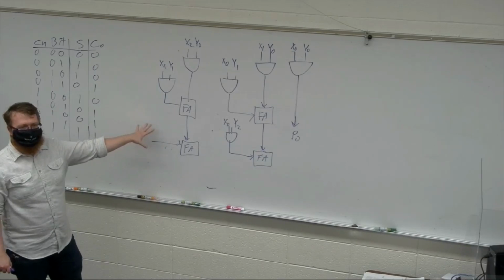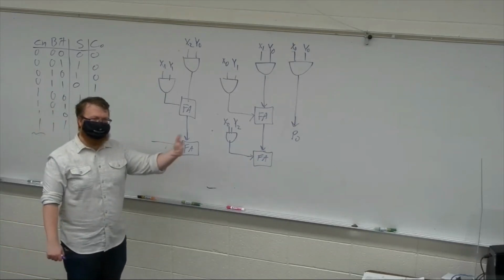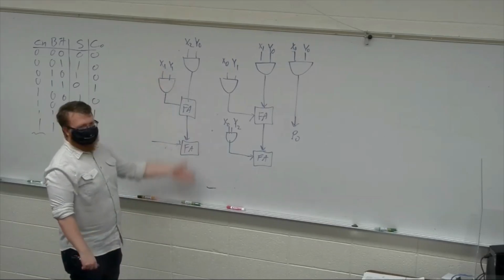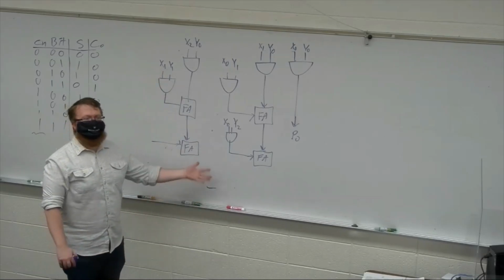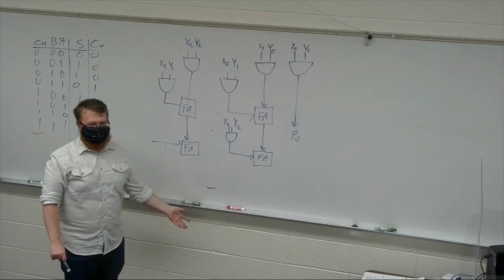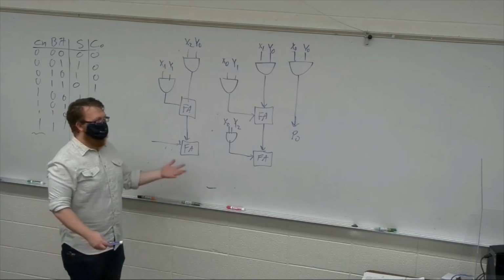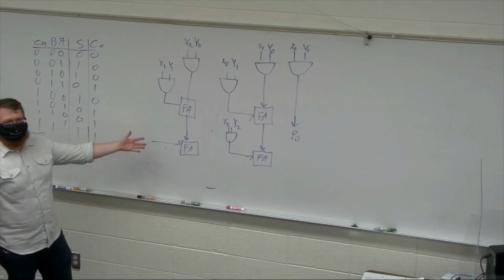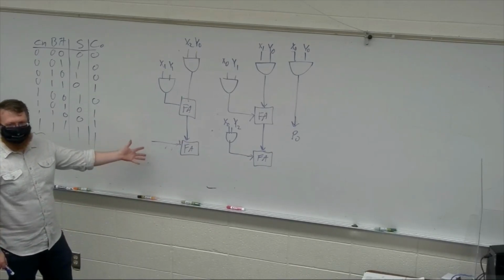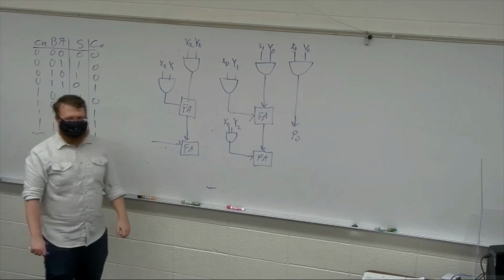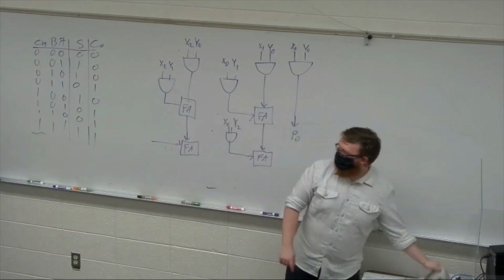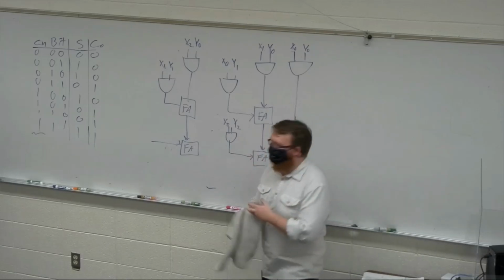There's no clock. There's no shift and then add and then shift and then add. It's just a cascade of gate delays, which is generally faster than your clock is going to be going. The downside, again, is that it gets huge. It's a massive circuit. But they work really well. This one is not clever, like the shift.